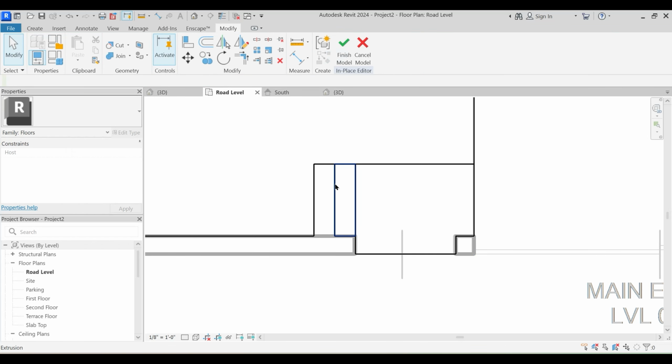As soon as you select this tool, I think this was not the case in earlier versions. Revit 2024 has changed this. Okay, parking to upper ground floor, and with that, just select this and move it. Yeah, fine. Bring it till here, and now we need to create the internal walls.